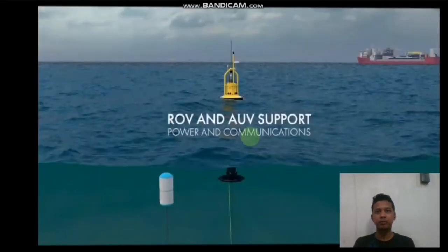To make efficient use of the force generated by the wave, we need some force reaction. In other words, we want the wave force on the float to react against another rigid body, like the one we see. Here is a suspended ballast plate, anchored to the bottom of the sea. So this rigid body stays in place while the floating part moves in relation to the waves.